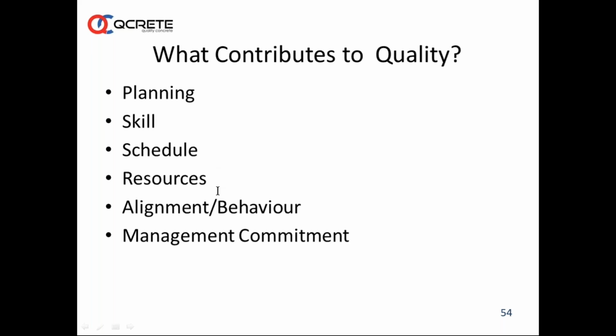What factor is more crucial if the cube strength variation against a set of cubes is more than 15%? Mr. Mukund Deshpande. Most important factor here, 15% variation on the mean. If we are taking three cubes and taking a mean, each individual cube should not vary more than 15% from the mean.